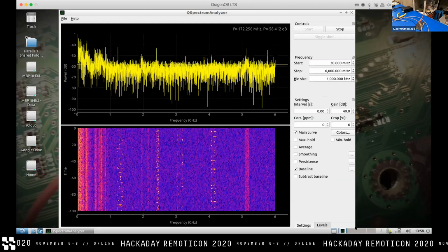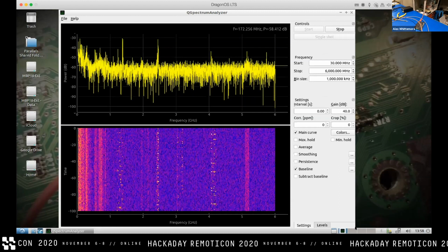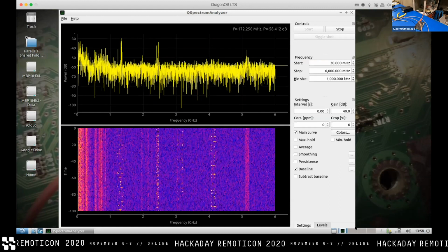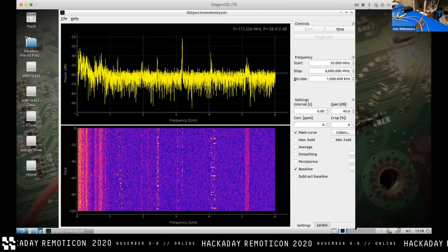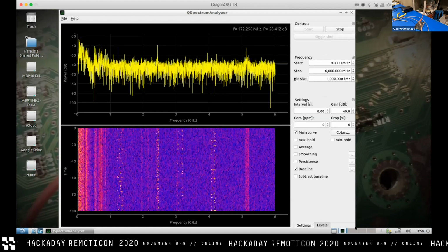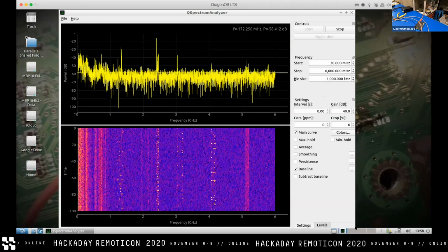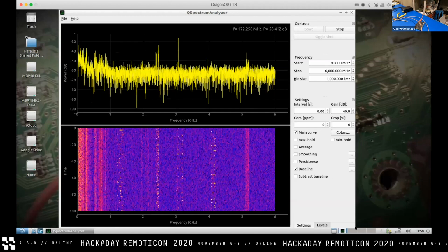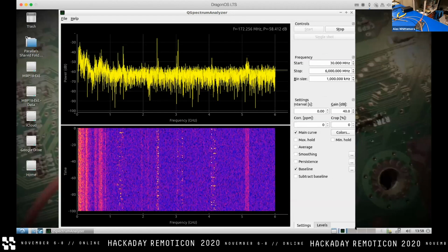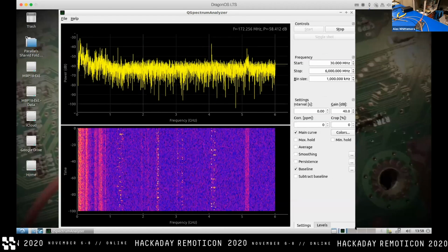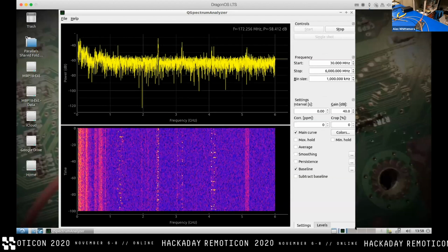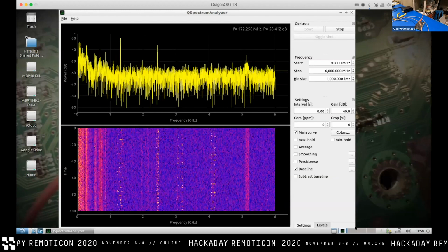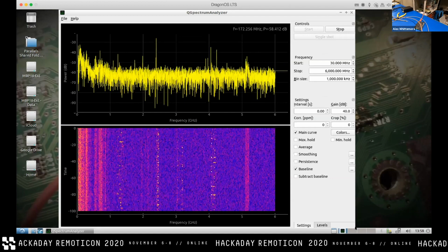And you might even be able to get away with doing that from a pre-compliance standpoint, because basically the issue that we have here is we have no idea what the power into our device actually means. Like the LNA isn't calibrated, the line losses are not calibrated, the antennas are far from calibrated. None of this gives us an accurate measurement.